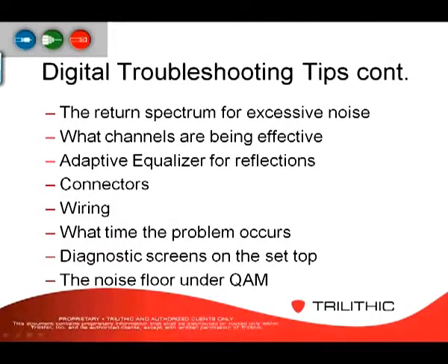You can check the return spectrum for excessive noise, because that's another thing we talked about in one of our other series. You know, that area accumulates a lot of that composite noise that's coming back from the network. So if you have a clean return, then there's a strong chance that your forwards are going to be looking pretty good as well. And then determine what channels are being affected, because remember that you can compress multiple channels